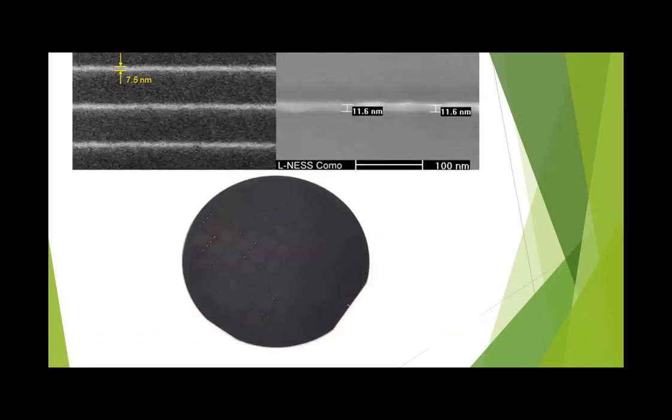This is from LNES, which is the Lab for Nanostructure, Epitaxy, and Spintronics on silicon. Silicon is one of the most common substrates to use EBL on. And so they were able to get incredibly small, about 7.5 nanometer resolution, basically little cavities there. So again, 7.5 nanometers there, 11.6 nanometers here. This kind of resolution is really revolutionary because most of the time you've seen resolutions of 20 nanometers or above. But this is showing the ultimate capabilities that we have at the moment for EBL.